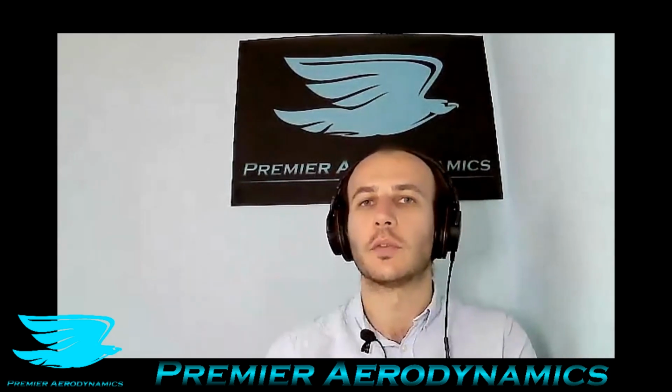Now, why is vortex lift so important? Why do we want vortex lift? Why do we want this delta wing? The reason this vortex lift is so important is not just because you can get a higher lift for the same thickness of airfoil, but because this vortex lift allows you to pitch your aircraft at a much higher angle of attack and still maintain lift.